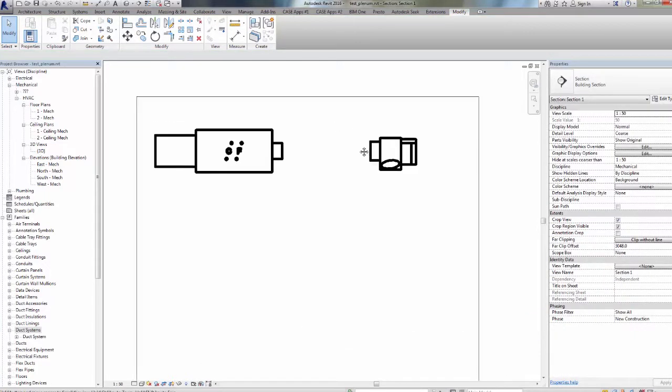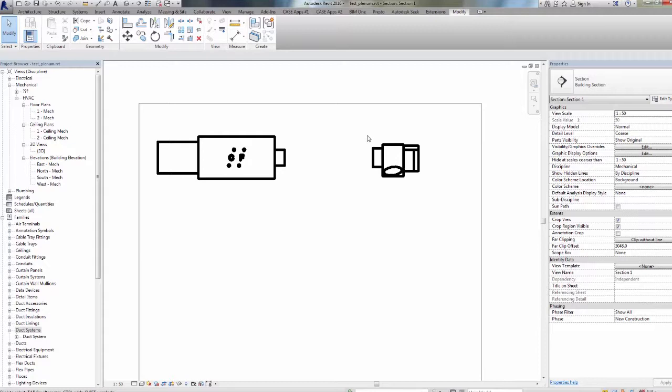We are now connecting the plenum to the indoor unit. In order to do this, with no intermediate element, the connector must have exactly the same size. The connector may have the same size, but not necessarily the same geometry. In the current case, both in the indoor unit and in the plenum, the connector's size and the geometry coincide. We could change the connector size and keep the geometry, but then we could not know the used dimensions unless we access the parameters.